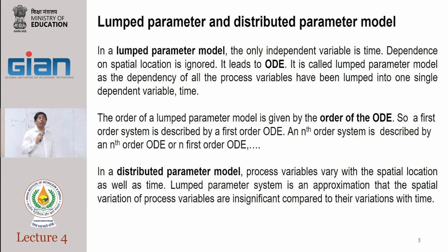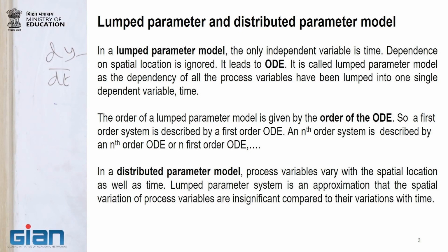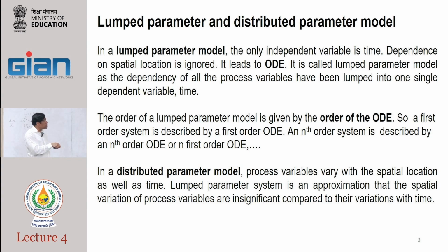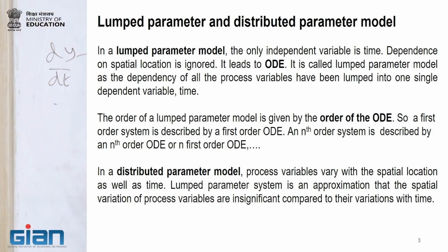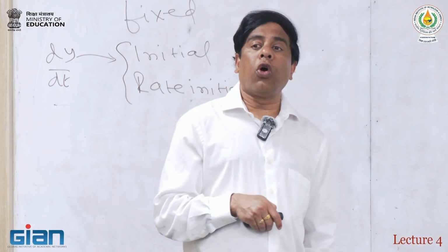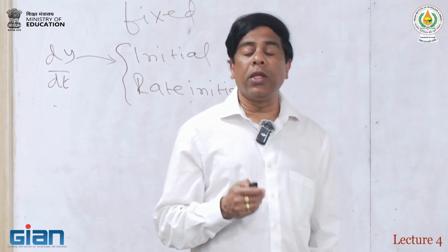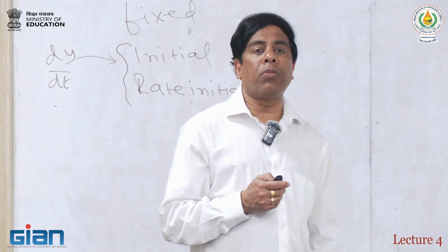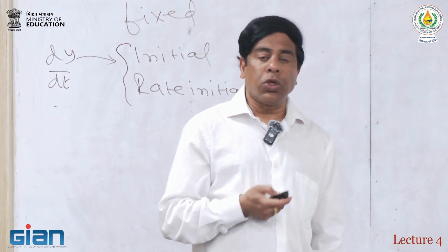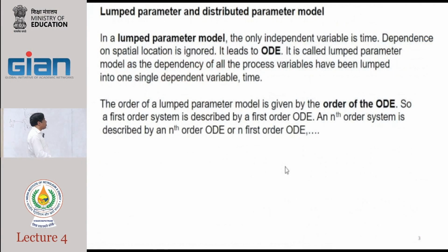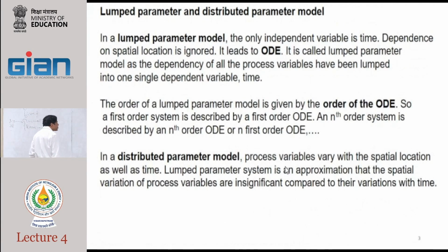In Aspen, this gives you all the opportunities, but there are pluses and minuses, and those are the things we'll be talking about. It's not straightforward, like saying, okay, if I have a second order system, I can approximate that with a first order ODE. They are mathematically equivalent, but they are not numerically equivalent. So those are the things that we need to keep in mind.